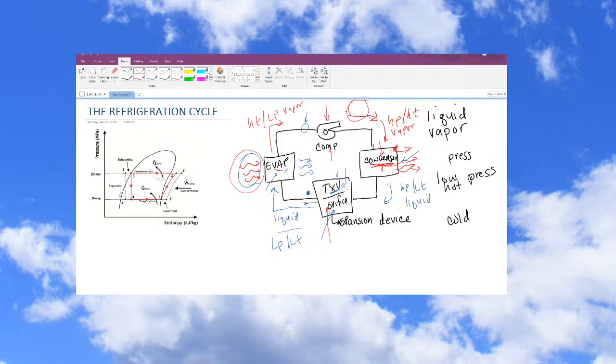And then add in, I have my intercooler, then my condenser, and then my radiator, right? Source of heat, source of heat, source of heat, right? This radiator, we want it to be all super efficient. We want to get our bigger, gigantic aluminum radiator or whatever we're going to run and hope that it helps a whole bunch. But it's only going to be as good as the amount of heat transfer that's available to it. So if you heat it up here, you heat it up here, and you get to your radiator, you're not going to have as good cooling.